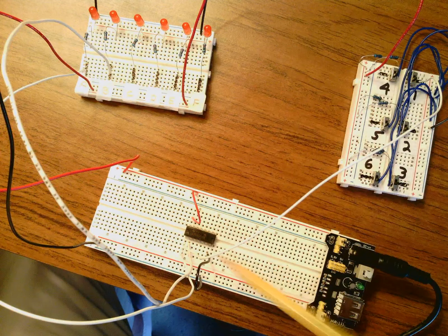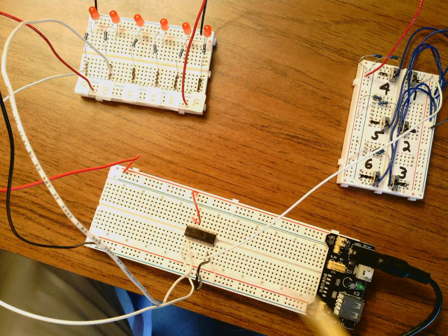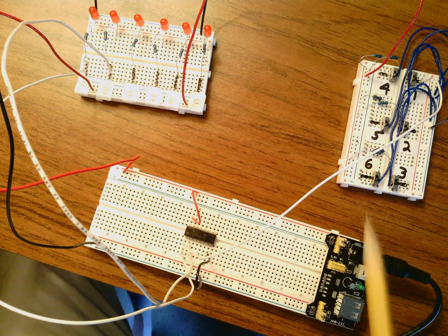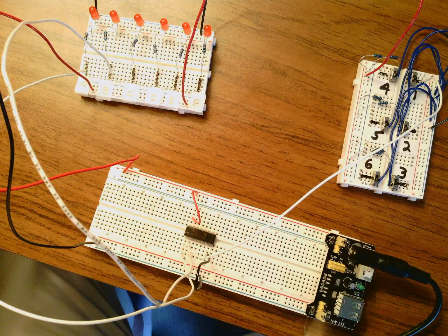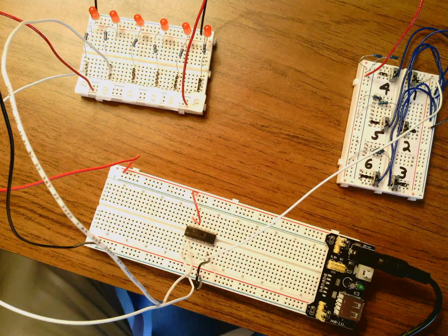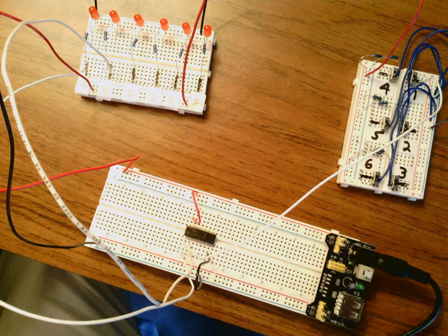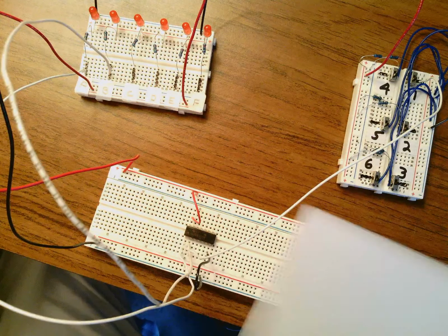But to make interconnections down on the board, you can use any color you want with the exception of blue, black, and red. Blue and black are always signifying ground. Red is always +5 VCC. Any other color you can use for data, but I'm using the white now to jump to switches and to LEDs.